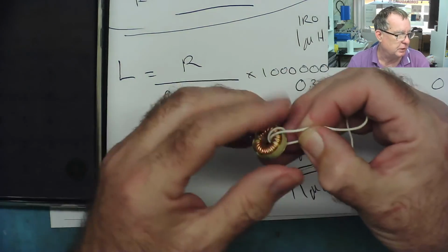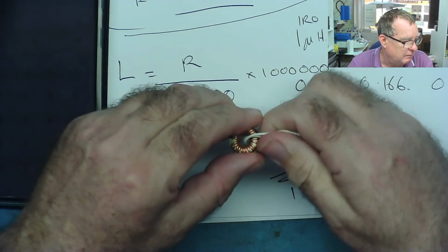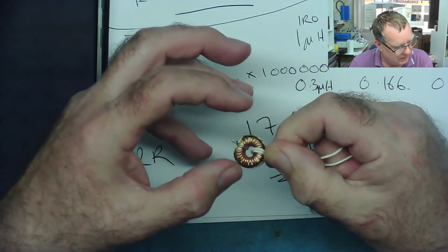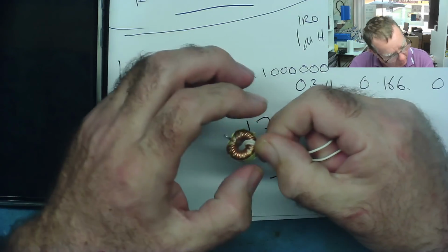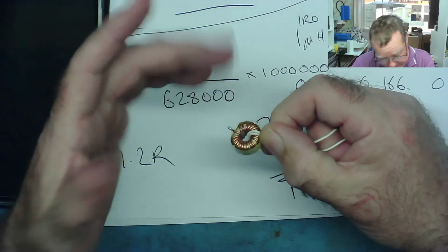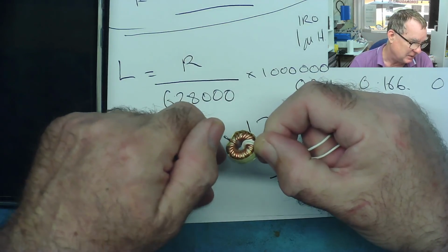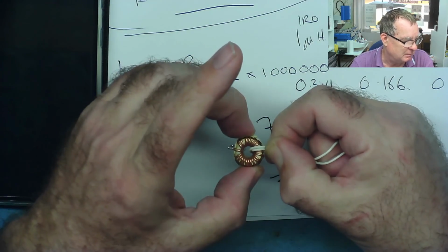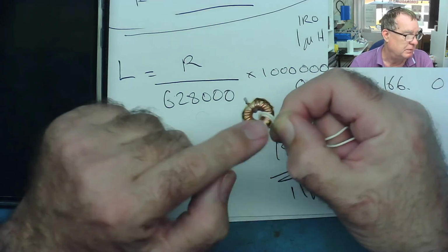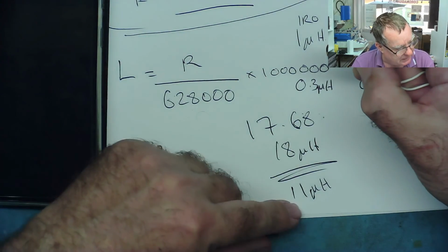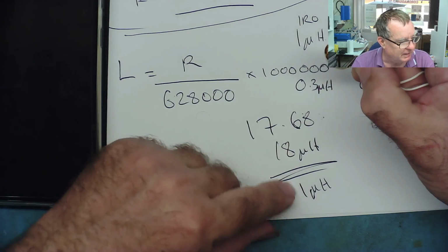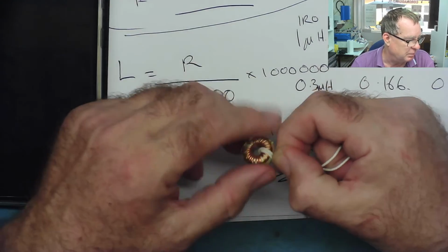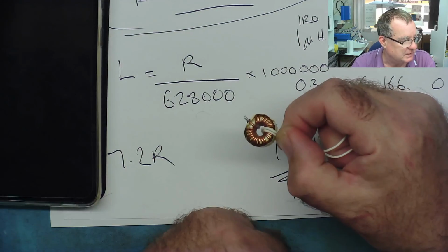If this inductor is part of a buck regulator circuit, the buck regulator works by magnetising this core. So it has a FET which turns on and magnetises the core. But before it can fully magnetise and become just a piece of wire, the FET turns off, and then it demagnetises. When the inductor is fully magnetised, that is known as saturated. If the inductance decreases because of a shorted turn, it will saturate at about 2/3 of the value it would normally saturate at. So at that point, the FET is still turned on. This is now a short circuit and you blow the FET. That's why shorted turns matter.